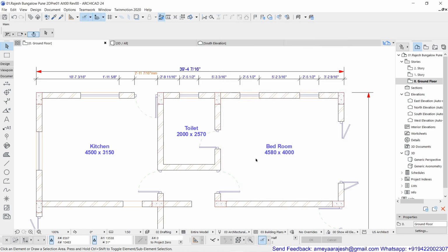Okay. And if I want to return back to the earlier one, you can see these buttons at the bottom in the status bar. You can check there is one option known as US architecture, and here is nothing but the dimension style button. So I'll just click on this, and from this list I'll fetch the one which I have designed. So my name and the WD metric. So that is the working drawing metric option.